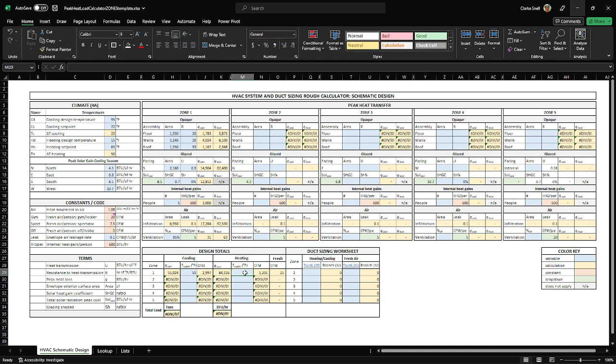And I'm going to say maybe 100 degrees for heating. It might be less if this was all a heat pump, and we can talk about that. The point is, now you see that we have a larger cooling load but smaller CFM, and a larger heating load, smaller CFM, right? What I'm trying to say is that the heating load is larger than the cooling load, but the amount of air we need to move is less because our set point is different, our supply temperature is different.